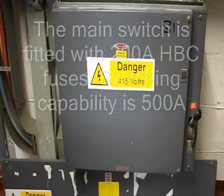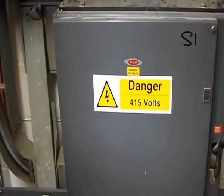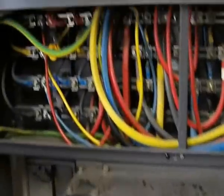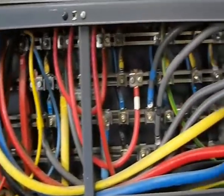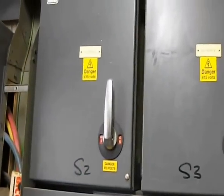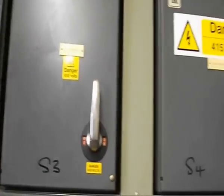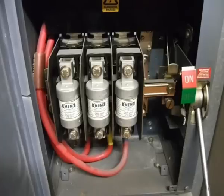The installation is controlled by this 500 amp fuse switch, and in turn the fuse switch will supply this butterfly chamber, from which the whole of the installation emanates. These switch fuses here are connected to the butterfly chamber via cable trunking.